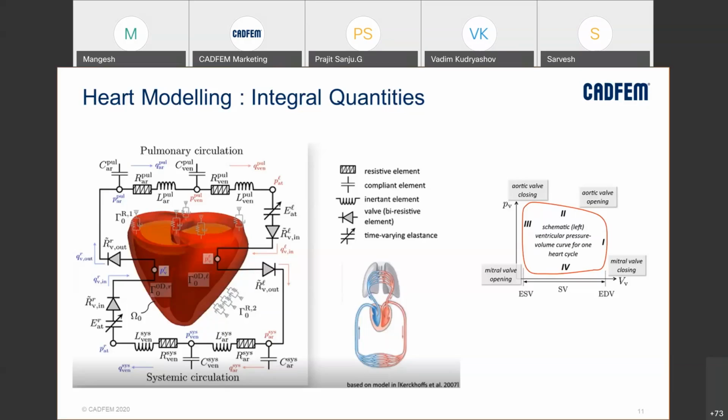When that flow rate information is available, we can put it in as an input flow rate for this network, and the overall pressure drop can be identified. It is the volume of fluid which is the difference between its expanded position and the contracted position. That fluid is what is going to be our flow rate for the network.